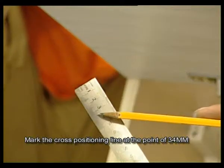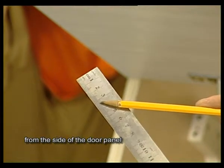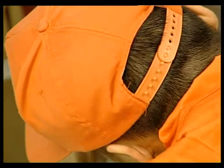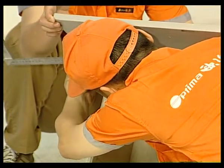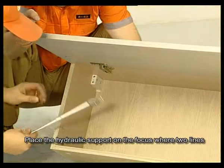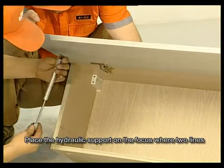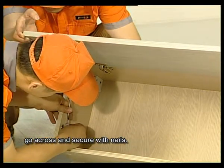Mark the cross positioning line at the point of 34 mm from the side of the door panel. Place the hydraulic support at the point where the two lines cross and secure with nails.